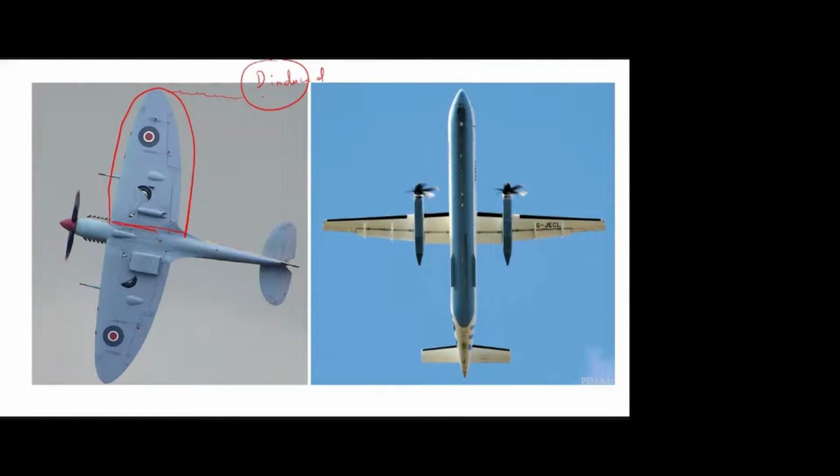We cannot say that the induced drag is 0. It produces the minimum wingtip vortices and the minimum induced drag. But manufacturing this elliptical shape is very difficult. So instead of this elliptical shape, we are going for tapered wings. For that purpose only, we are using the taper. Is that clear?